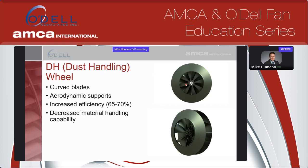But the trade-off there is we have decreased material handling capability. And as we get more efficient, these fans are even quieter than your paddle style wheel. This wheel was developed in the 70s when there were some energy concerns. And obviously, as energy concerns have grown, these style wheels have been developed and continue to be developed for better efficiencies while still being able to handle dust loads.